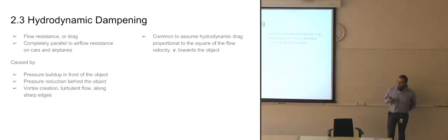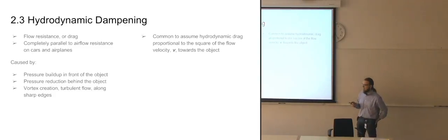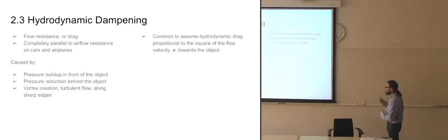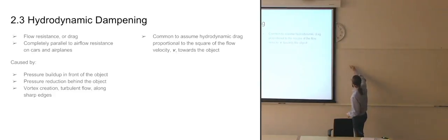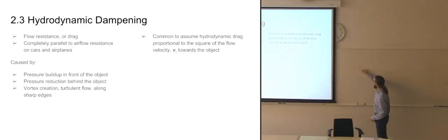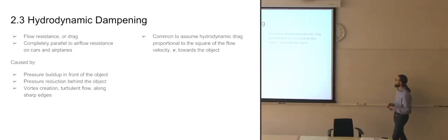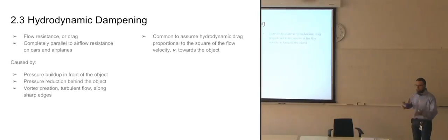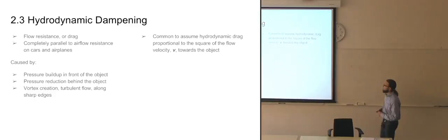The good thing about that is that DNV have recommended practices of how to do calculations on marine operations. If I remember this, we used this one in my bachelor thesis, it's DNV RP, for recommended practice, and then it was H103, I think it is, which is the recommended practice for marine operations, so basically lifting and lowering stuff out at sea.